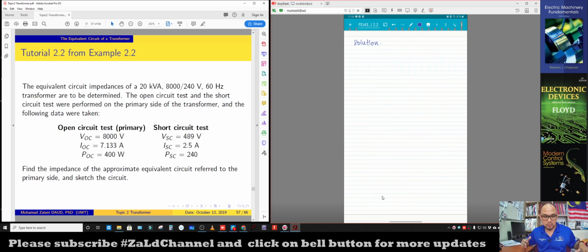Okay, so because we have already got all of the values, now we start with the voltage at the primary and the voltage at the secondary. So what we do is firstly determine the turns ratio, which is a equals 8,000 divided by 240.